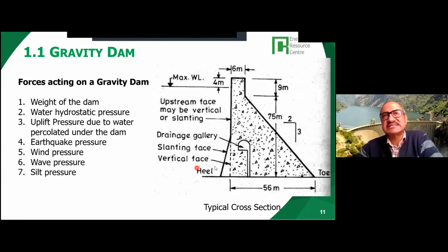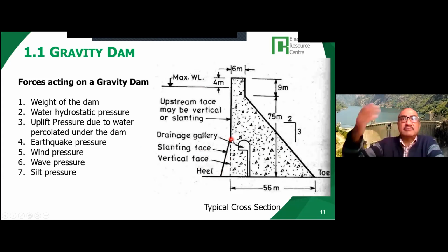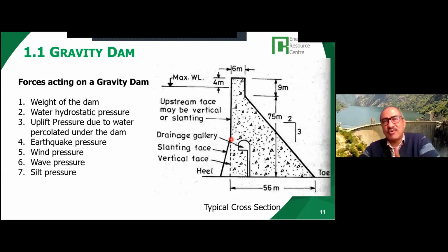So as I was saying, one is the dead storage, but after 50 years the dead storage will be filled. Then you have to decommission the dam. So after 50, 60 years, the dam will not be functioning as it should, number one. Number two, to really reduce the problem, you can control the catchment by watershed management and conservation. You have check dams upstream so that you don't let the sediment come all the way to the dam.